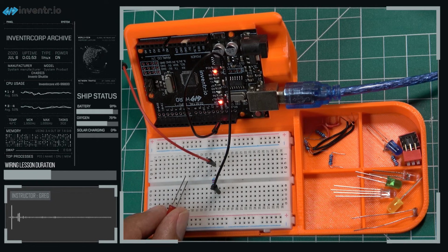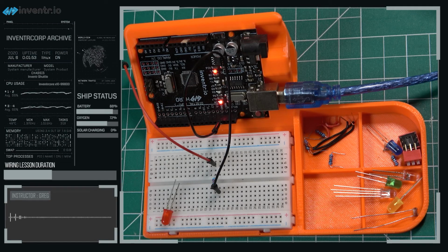And so this is why we'll always pair our LEDs in series with a limiting resistor, which will more or less guarantee that the LED current can't exceed the maximum allowed by the limit resistor. Now, in fact, this discussion isn't exclusive just to LEDs. Anytime we have current in a circuit driven by a fixed voltage, we will make it a strict practice to always include current limiting resistors to keep all currents within appropriate safe limits.